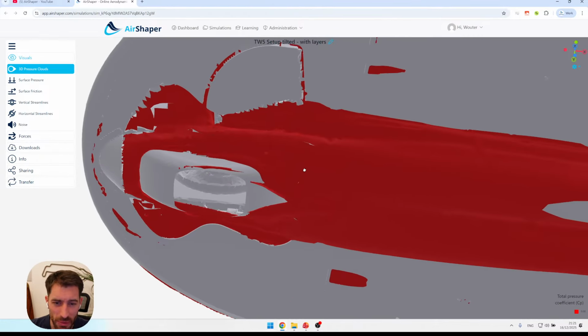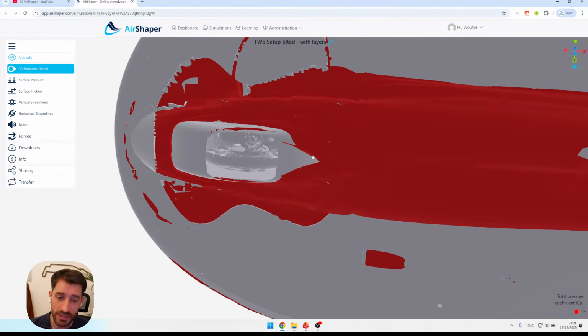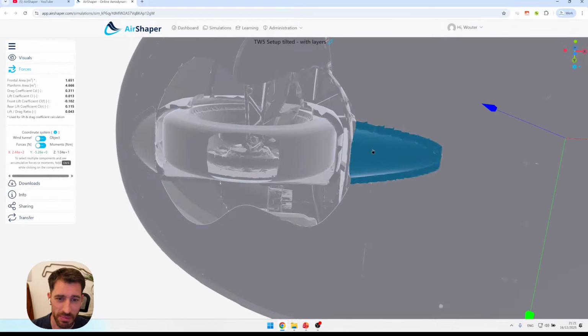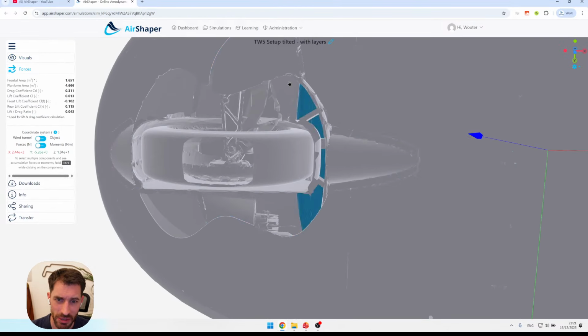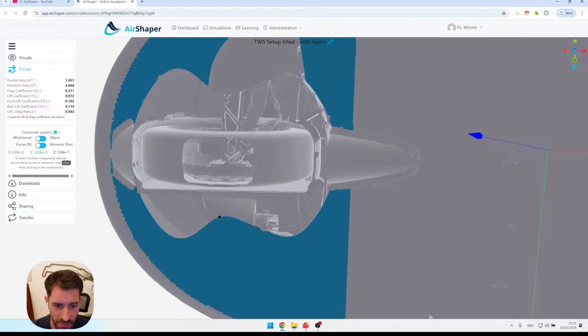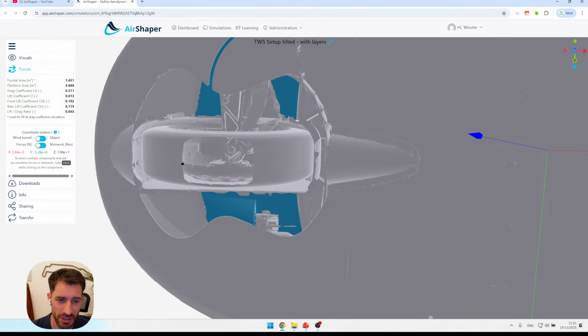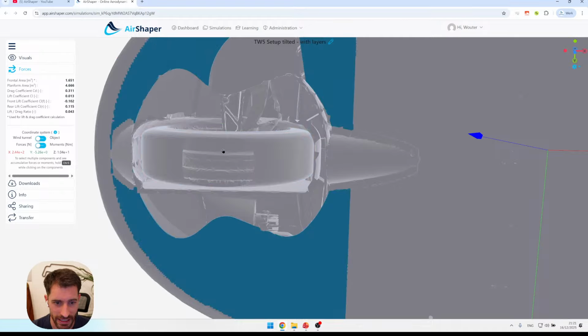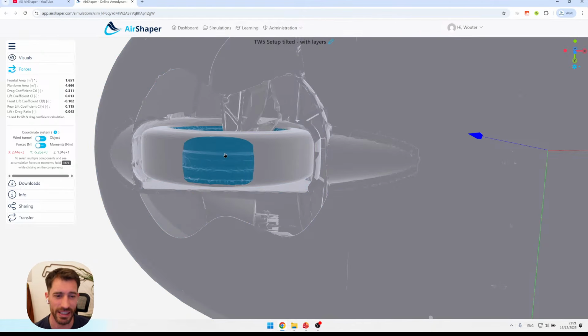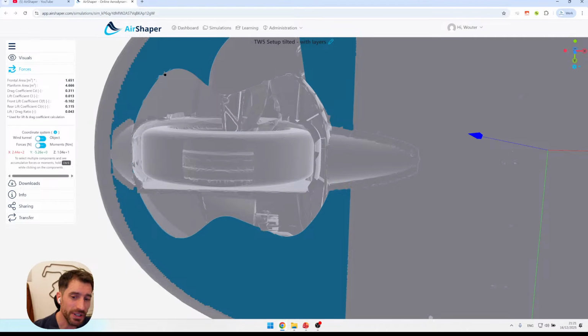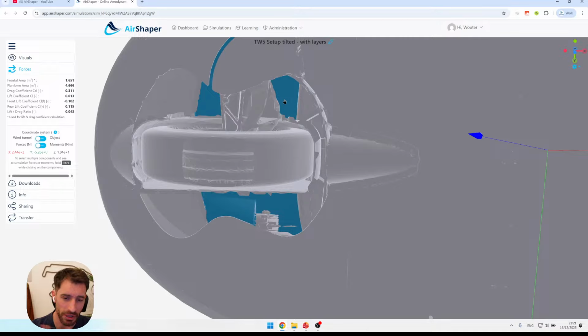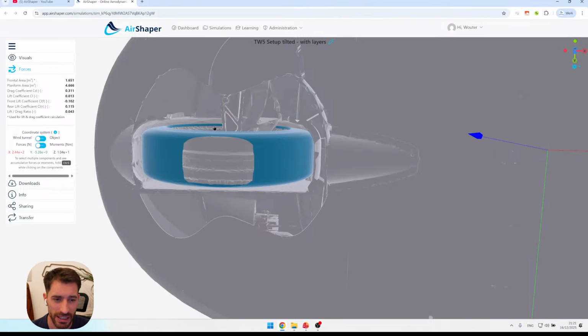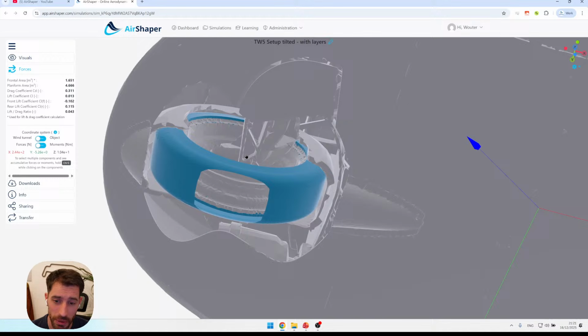One of the key problems with this car was what they call the potato shape. Twike dubbed this the potato shape, which is this infinity symbol shape that you have here, which allows the wheel to just rotate left and right as you want to steer. As you can imagine, if you rotate this wheel to the left, it will be aligned like this. If you rotate to the right, it will be aligned like this. So you need clearance. And even though we're currently looking at a cover that will rotate together with the wheel to close this shape, most of the design optimizations were done for an open shape.